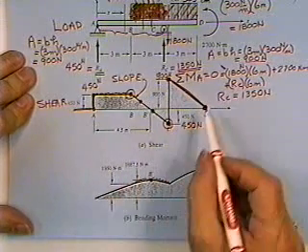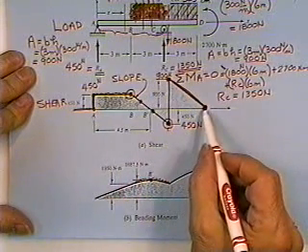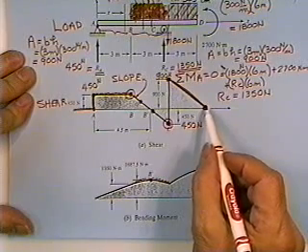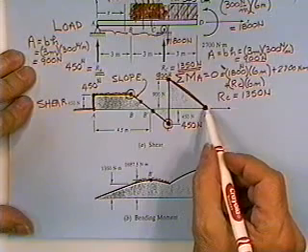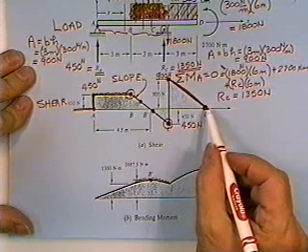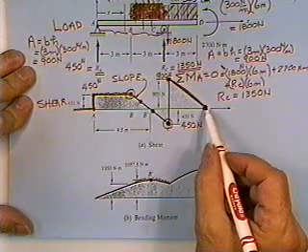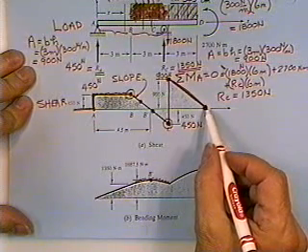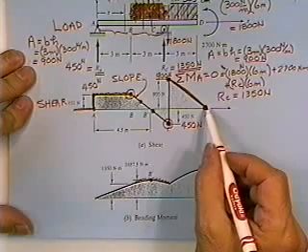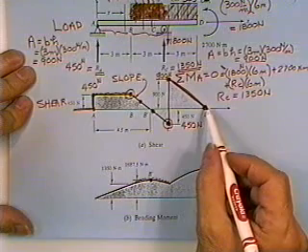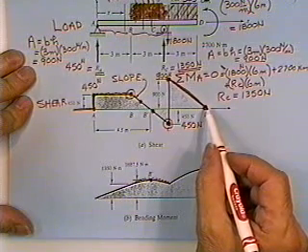Now at that time we cross something kind of weird, and it is a 2,700 Newton meter twist. But this shear diagram is for telling you up and down movements of the diagram only. It's only for shear. So even though the 2,700 Newton meters is at the end, I wouldn't care if it was at point B. As I crossed it, my shear diagram would not hop up, because that moment doesn't point up, and it wouldn't hop down because it doesn't point down.